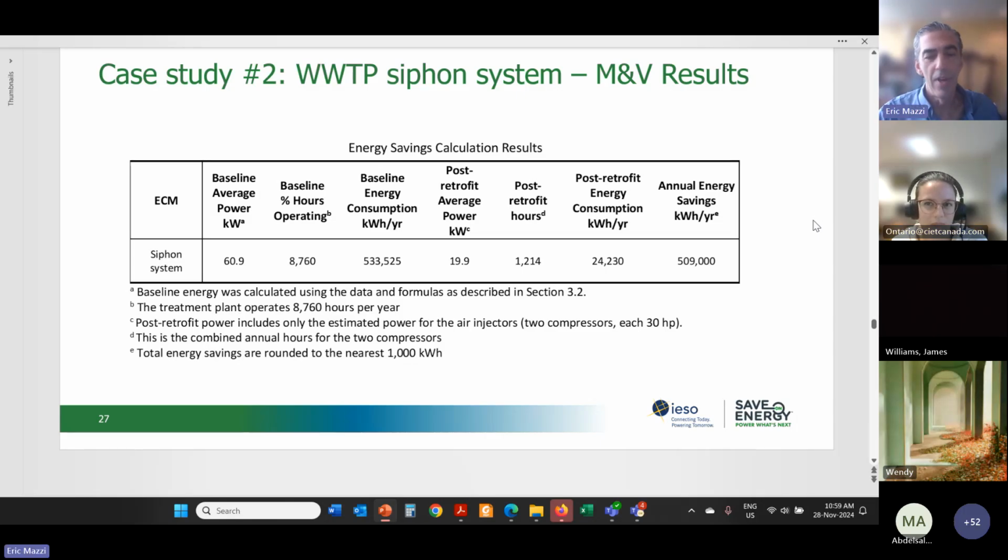I guess the argument can be made, but fundamentally, the baseline system could have very well been built, with pumps without injectors, and that pump motor power could have been measured, but it wasn't built. So the best thing we can do is estimate it using Bernoulli and basic fluid mechanics. For the as-built system, the electricity consumption comprised entirely of these injectors. So it's definitely following the method, in my professional opinion, and there's no better way to do it.